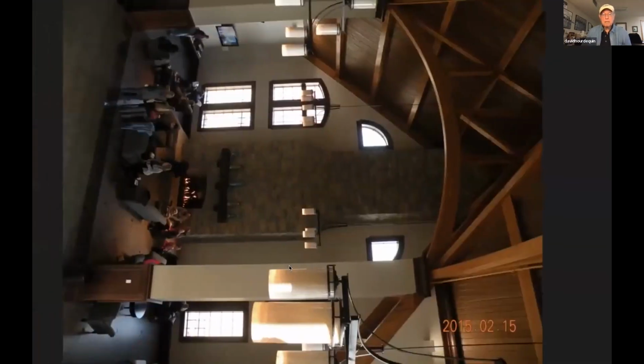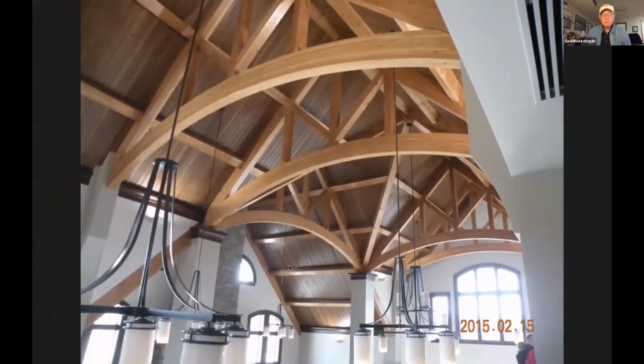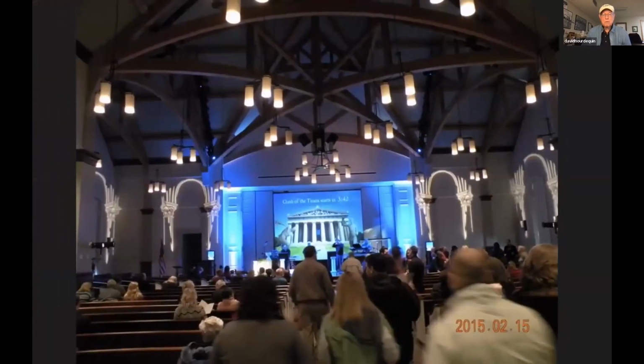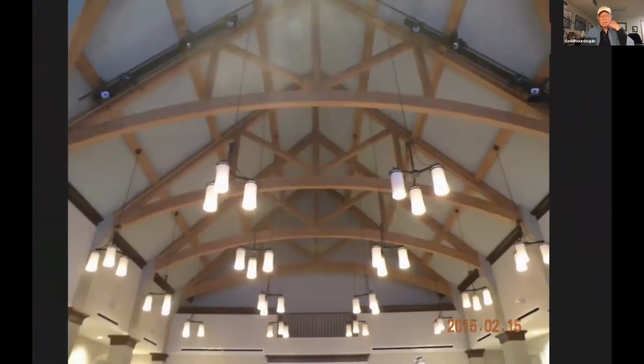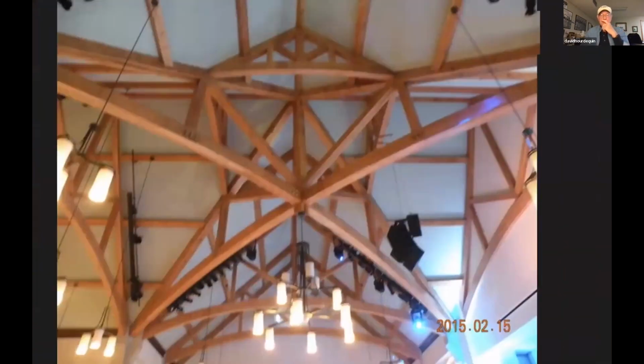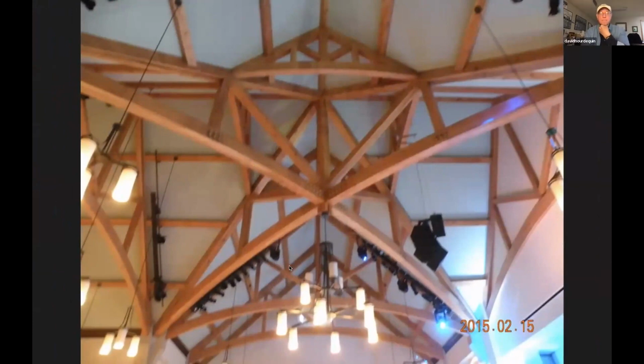So let's go back to the middle. We'll stop right there. So any questions? Oh, by the way, the tension in these trusses was about 70,000 pounds, I'm thinking, something like that. How many bolts we got in here? 2, 4, 6, 8, 10. So you know, that's quite a few. Probably at 4 or 5 kips, so 50-60,000 pounds of tension at least in that bottom chord.